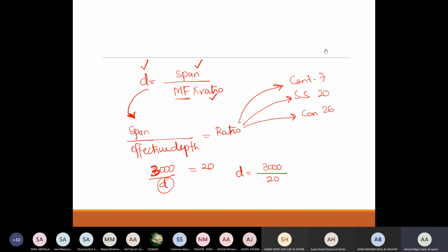If you remember, shear force was a function of coefficient multiplied by W multiplied by L. Moment is a function of coefficient multiplied by W multiplied by L square. Do you remember? If your loadings are small, it means that your shear and your bending moment are small. So once again, a slab normally does not fail in bending or shear.